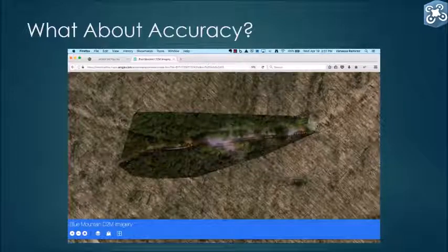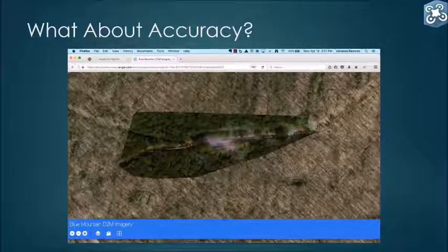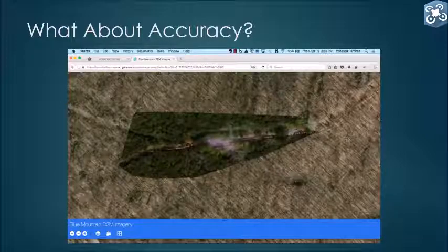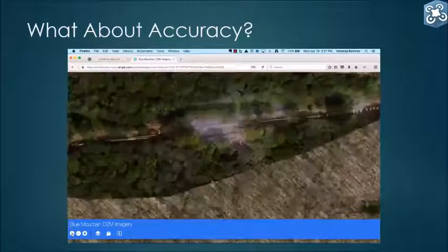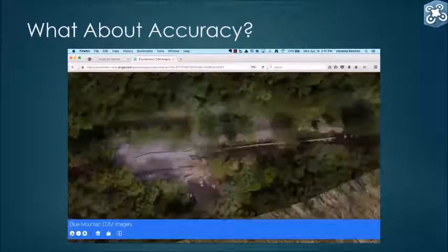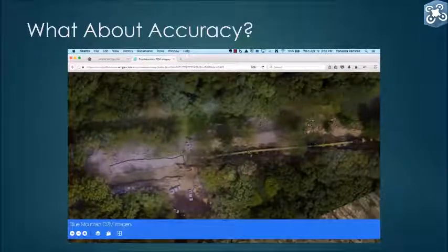Drones are a new and exciting concept that can easily be incorporated into GIS. In this particular example, we wanted to see how we could utilize drones in the field to augment the as-built survey process. So what we did is we actually flew an exposed right-of-way and in-ditch replacement out in the field utilizing a drone to get the high-resolution imagery that you see on my screen. You can see here it's extremely detailed and gives you the ability to visualize the weld points as well as the rock jacket on the pipeline.